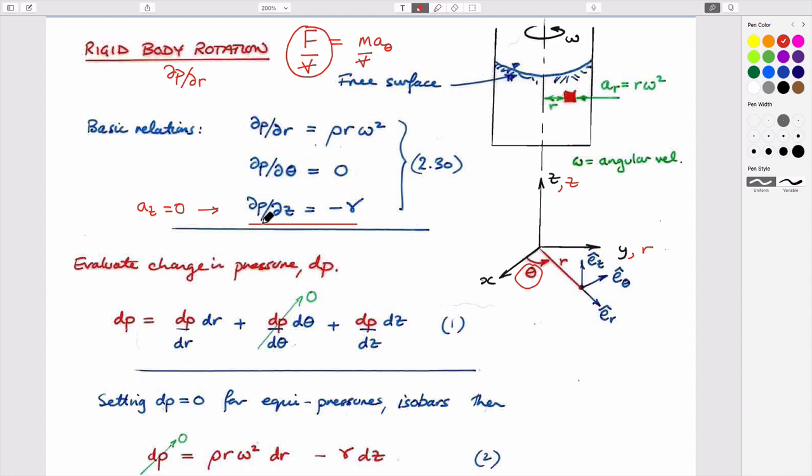So we can define pressures in terms of these. The only one that will be different from us is going to be the one in the r direction. I've derived it in the past, but I won't derive it here. We can also write this acceleration as equal to v squared over r. So this is also equal to density multiplied by the velocity v theta squared over r.